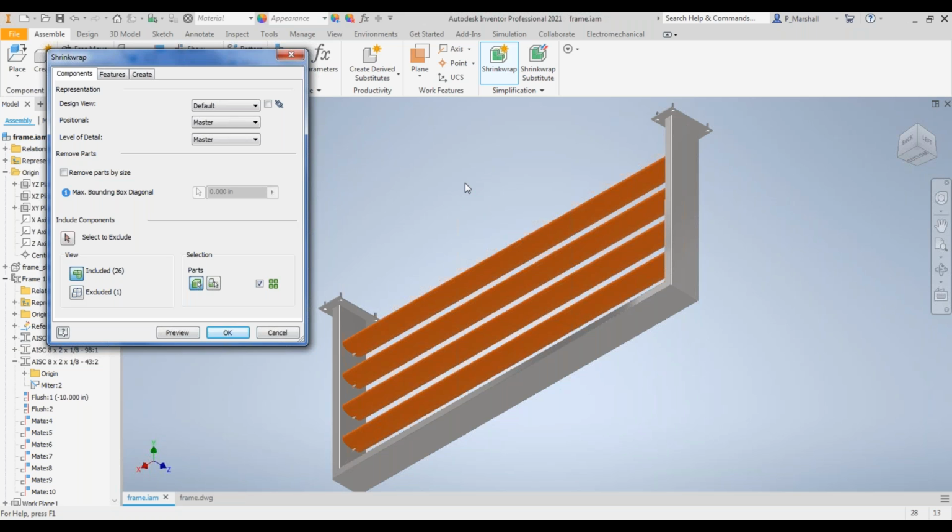First, the manufacturing model is typically way too detailed for the architect. Making a Revit family with all of that detail would create an overweight, bloated object, which would impact the performance of the BIM model. Second, you may have proprietary or intellectual property in your model that you don't want to share with others. And third, by keeping the manufacturing specific details in-house, you can optimize your internal process without having to coordinate with others.